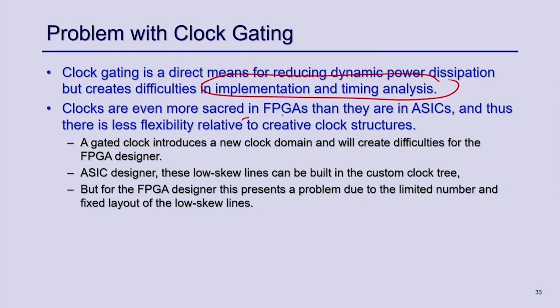Specifically for FPGA, we have only one master clock line. So if you have multiple clocks, they will be routed through the normal LUT structure, and that will create a lot of delay and a lot of problems. So multiple clock domains are not a practice for an FPGA target, specifically this gated clock. That may not be feasible in an FPGA target.